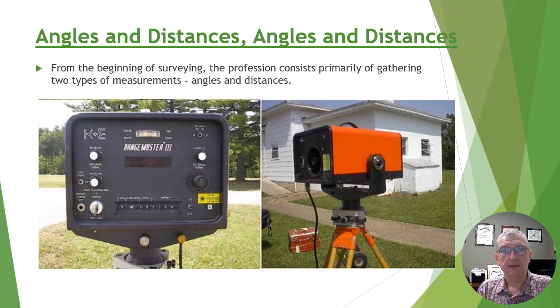And even in this current day of the 2020s, we can go back to precise surveying that was done with high precision theodolites and calibrated steel tapes, or early total stations and electronic distance meters, and those measurements, precision wise, are on par with what we do today. They just had to go to a lot more work to get it done.